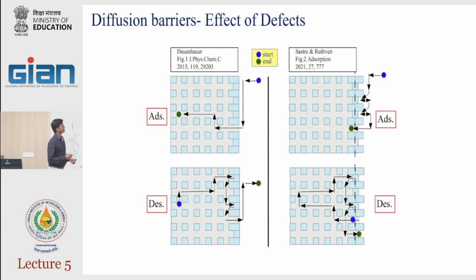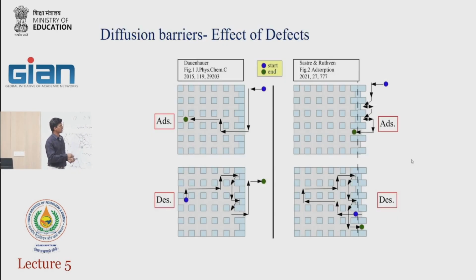It's an extreme case where you see a gas molecule adsorb and travel till the end, where it finds that all the pores are blocked at the end, right? You see the gas molecule enters from here, it puts all the effort to come here, but it wants to diffuse and this pore is blocked. This is one kind of situation people try to model to see how it affects the diffusion, because these molecules have to travel an additional path to locate the pore which is open, right?